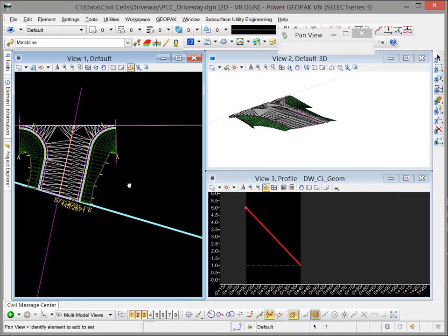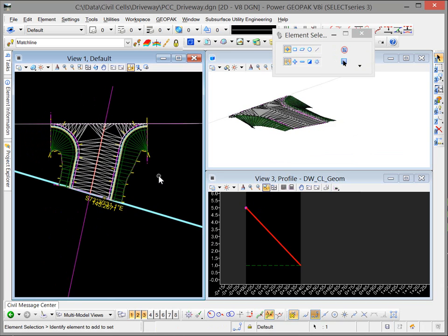One thing that I suggest is when you get to the point right before you place your surface template and your linear templates, to save that off as a base pavement civil cell. And by doing that, then you can make several copies of that and include different linear templates or different pavement designs.